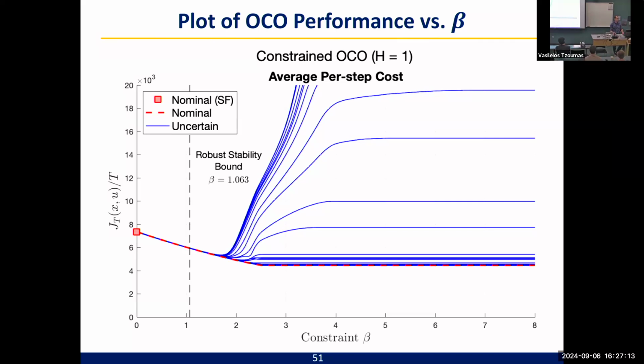The short answer is yes. So first off, if t is rolling off, the inverse of t is rolling up. If you take a snapshot of what the recursive least squares is doing towards the end of the simulation, it's got very high gain at high frequencies, which is also part of the reason it ends up being very sensitive to model errors at high frequencies, because you've just added something with very high gain at high frequency, which is not a good property. And not even to worry about things like right half plane zeros, then you've got these inversion effects. So most of these proofs would have assumptions about whether there are right half plane zeros or not for stability. Yeah, I've kind of sidestepped that in this talk.